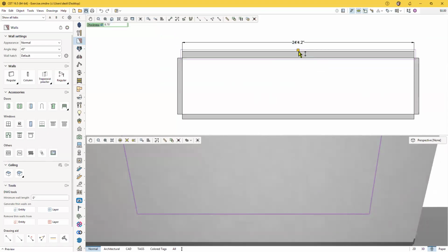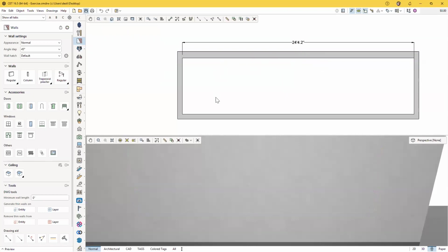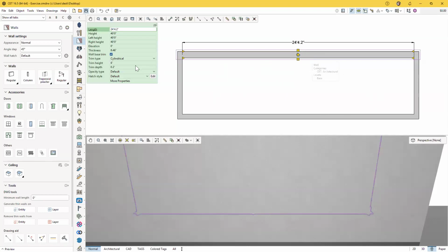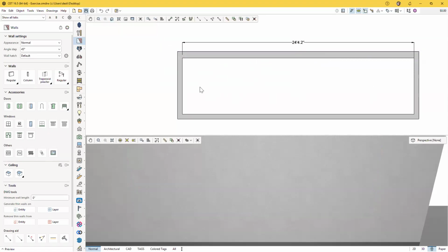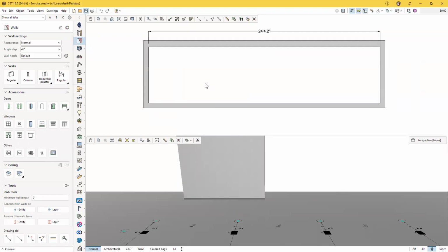You can stretch away from that interior space to create that thicker wall while maintaining the same size inside. If you use those quick properties, occasionally it will not stretch in the direction that you intend to, and it's actually changing the interior space size, which can make space planning kind of tricky, and you'll end up with a space that you do not intend to have.